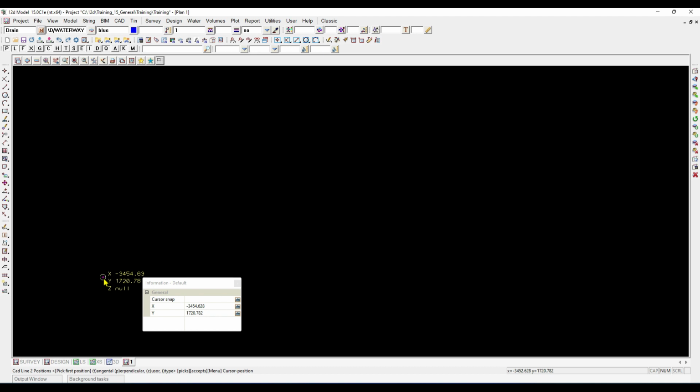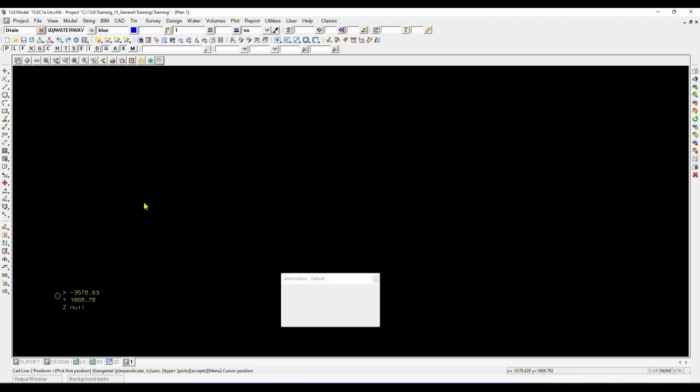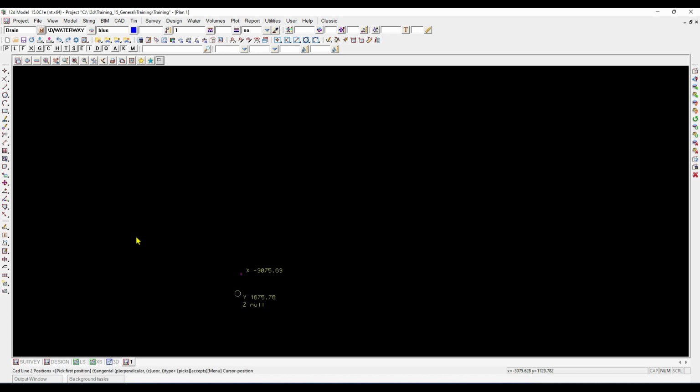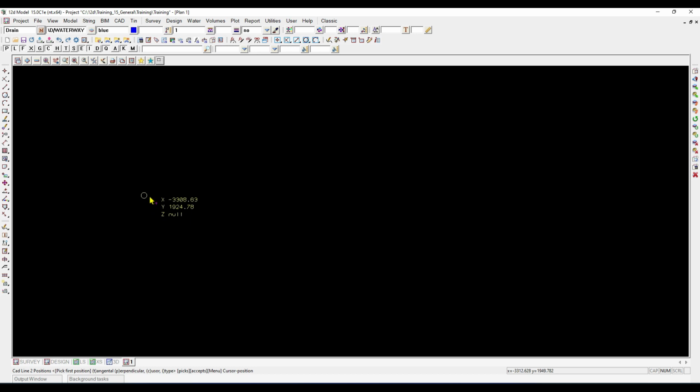So until you're satisfied that that's the position you want to start drawing from, you can simply do what we call the 12D shuffle and shuffle around and keep clicking your left mouse button. And when you come to a point where you want to start drawing, you go, oh yeah, okay, I'm ready to start drawing here. You simply select that position by clicking your middle mouse button.